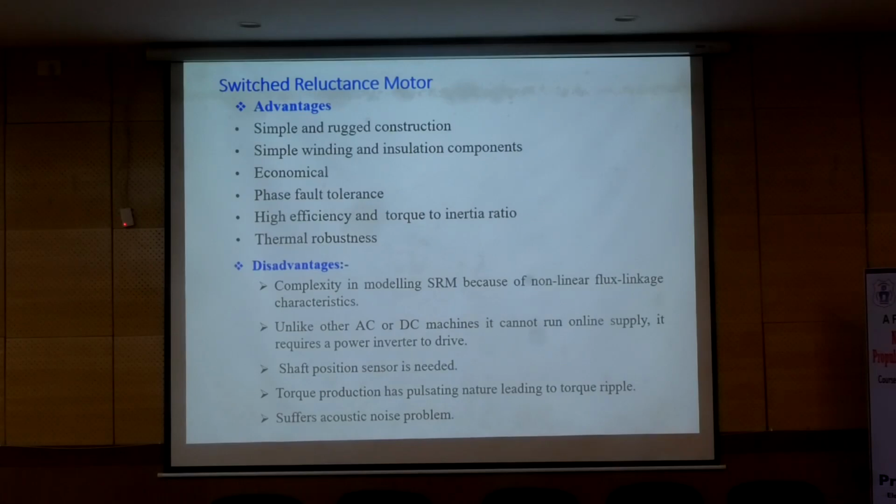But when we use these power electronic converters, the switching frequency is related to the switching pattern in the PWM process. As the switching frequency increases, switching losses will increase.